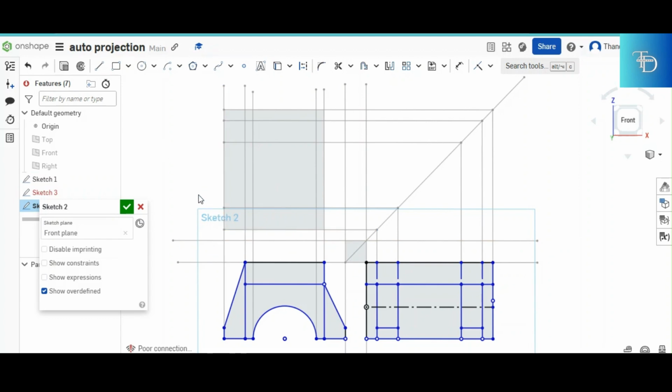You start with what is almost obvious, just like that part right there. So what are you going to see from the top side? You should start from there, exactly from there. You should map it with the top side of the front view. So where does it go? It goes there, and then it ends where? It ends there. And then from there, you already know that there is no gap at the top of the what? At the top of the component.